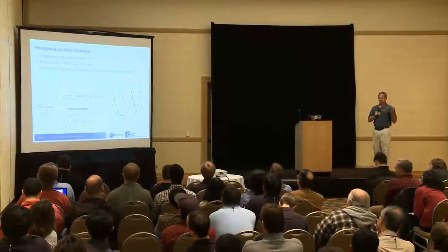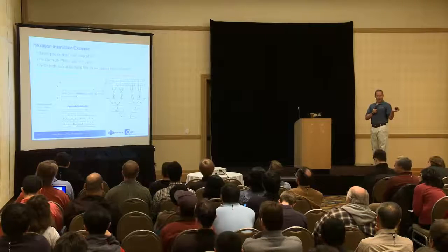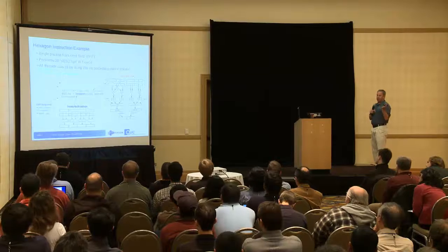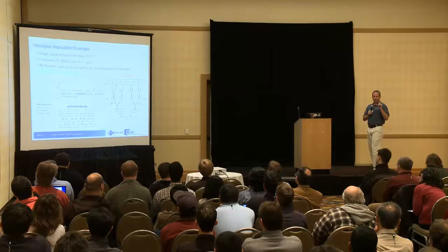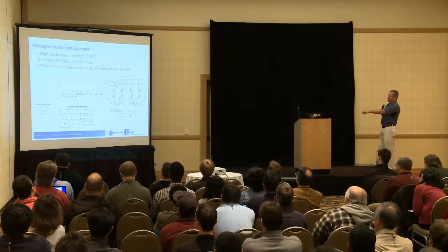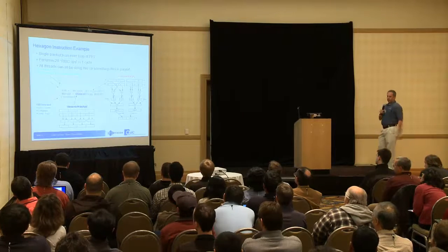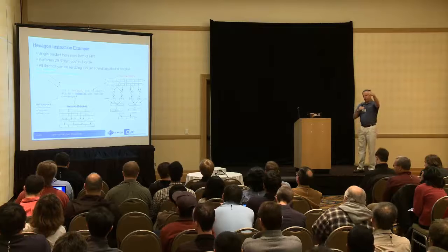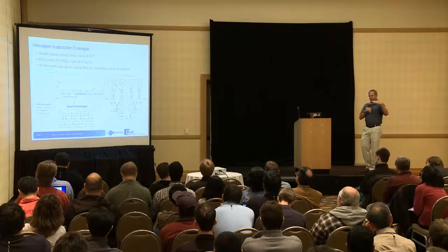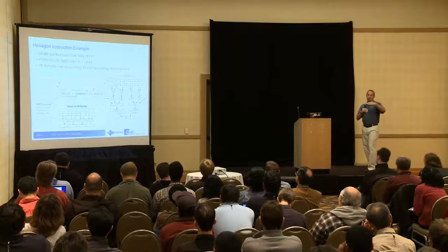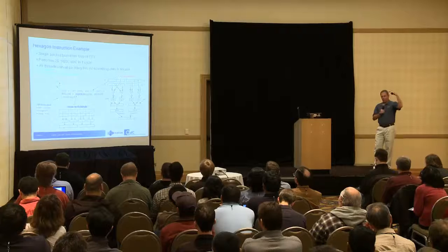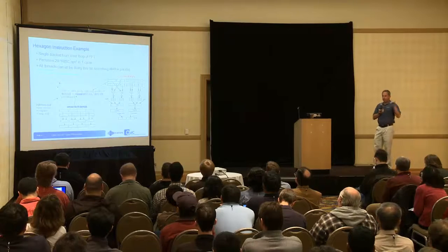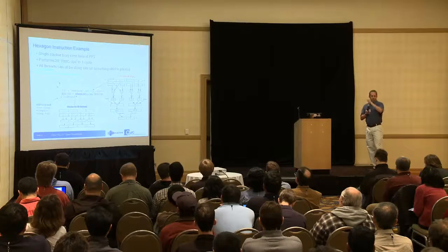If you were in the OpenCL talk a little while ago, the guy talked about packetization. And it kind of threw me for a loop because we talk about packetization in terms of forming packets for a VLIW instruction. So the syntax here, if you see the curly brace, that indicates a VLIW packet. And the semantics are what they would be with a traditional VLIW, where at the beginning of the cycle, you read the register operands, then of all the instructions, you do the computation and then you write them back, which is not necessarily the same as if you execute them in sequential order. For example, if I say R0 equals R1 and R1 equals R0 in the same packet, that's actually a swap, which is a different behavior than if you execute them sequentially.